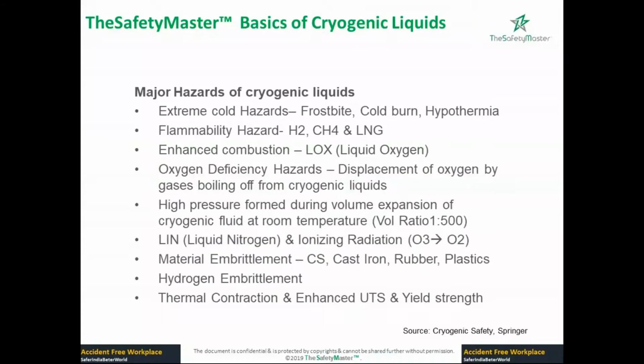The moment you hold the pipe, there'll be some ice formation, and the skin will stick onto it. You won't be able to take your hand off, because immediately the moisture will condense, and the skin will peel out, or you will have a severe injury on your hand.